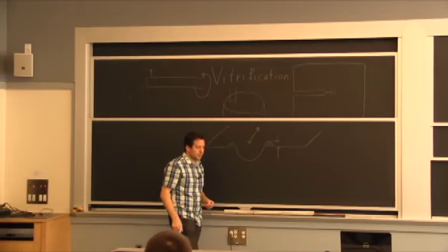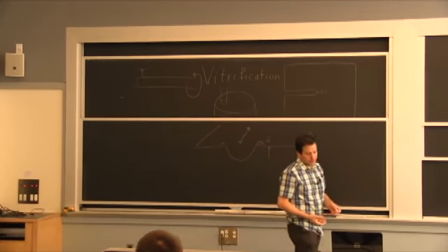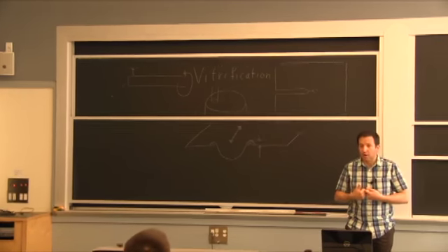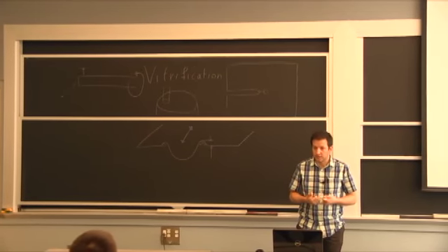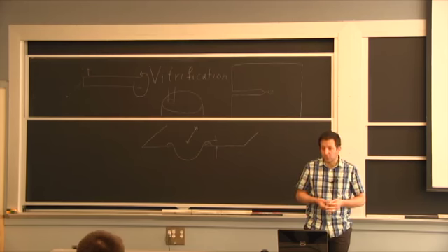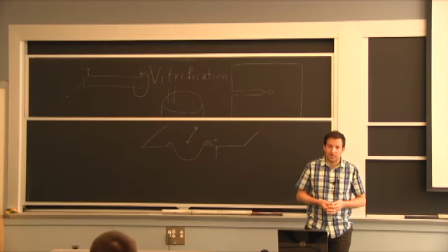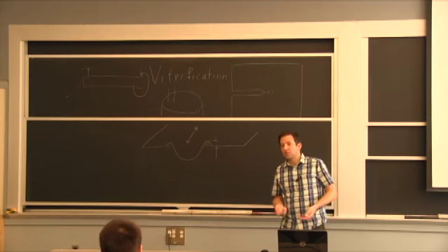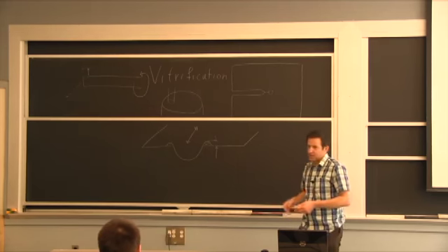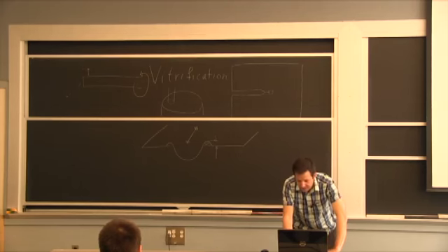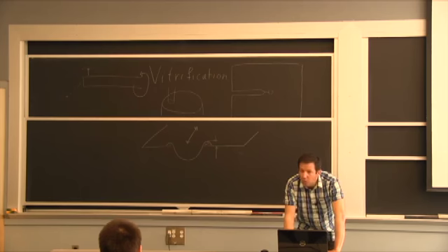When you have these composites, one advantage is if you start deforming, you can start having the particles contact each other, the hard tungsten carbide, and that is increasing your strength, your compressive strength. It's not linear. The more you deform, the stronger you are. And that contributes to the wear resistance. In addition to having the hard particle, in some situations, you can have no wear.